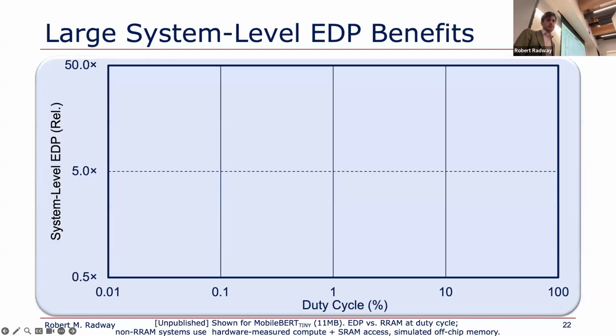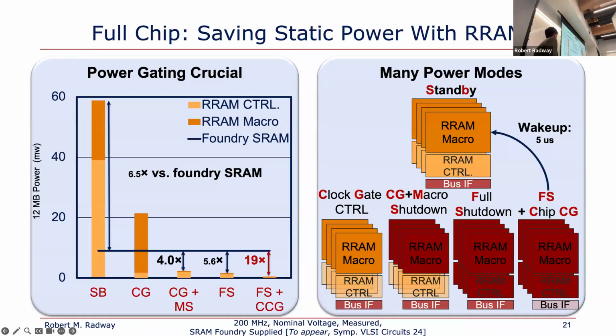And so if we take the system and we look back at that, yeah, go ahead. So to get these power savings estimates here, do you have to build out the system or can you do this in simulation? This is from measurement, but we had simulation results that projected this as well. So in chip design, you have power estimation through activity propagation, which I'm not sure how much this class will know, but basically you can estimate how often each of your logic gates is switching, and that tells you how much you're charging and discharging the parasitic capacitance in that cell.